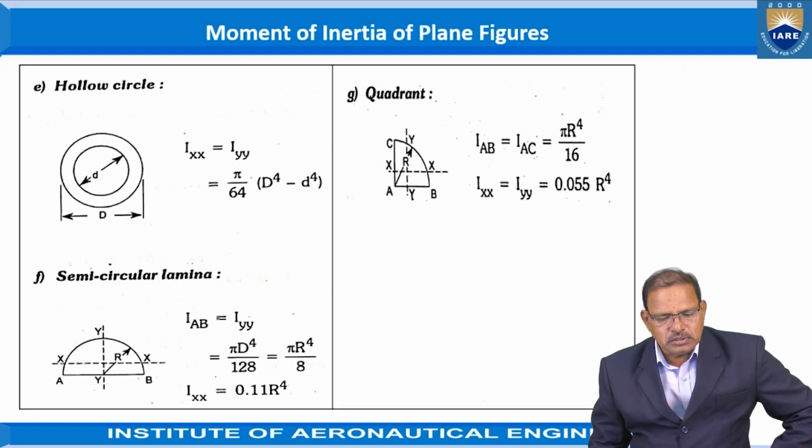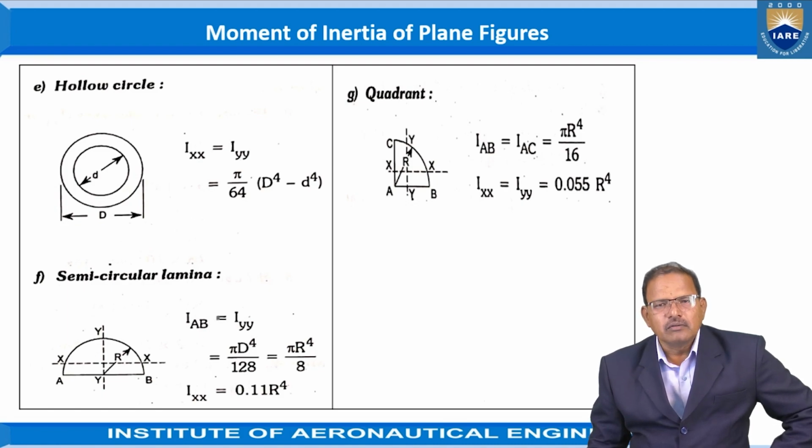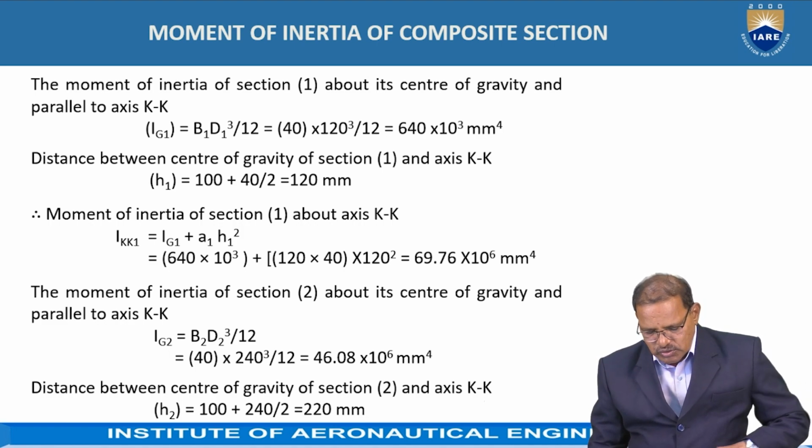But sometimes, if the figure is symmetrical about the y-axis, that is the vertical line, that axis is taken as a reference line to determine the position of the centroid. Similarly, if the object is symmetrical about the x-axis, the x-axis is treated as one of the reference lines to avoid the calculation of determining the position of the centroid, because it lies on the same line, that is, y-c is treated as 0.